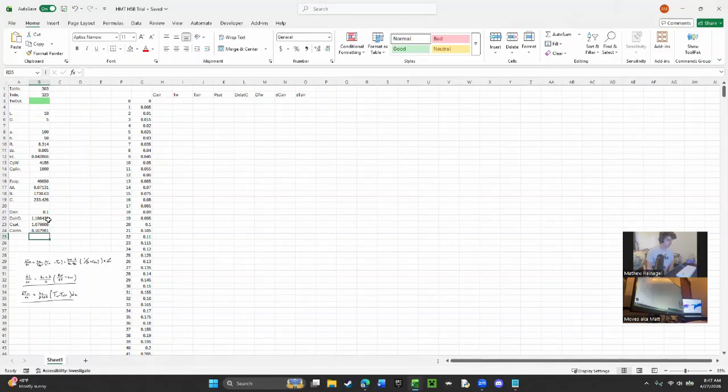Think of this as we know what the concentration of the fully saturated air is. And so getting it initially, you just multiply it by the density of the air coming in, which was given to us already. So now we have to do the Excel solver method. Excel solver works if we guess an answer first. So I'm going to do the same one that we did in lecture. I'm just going to guess that it's the same as the temperature of the air coming in, 303 Kelvin.